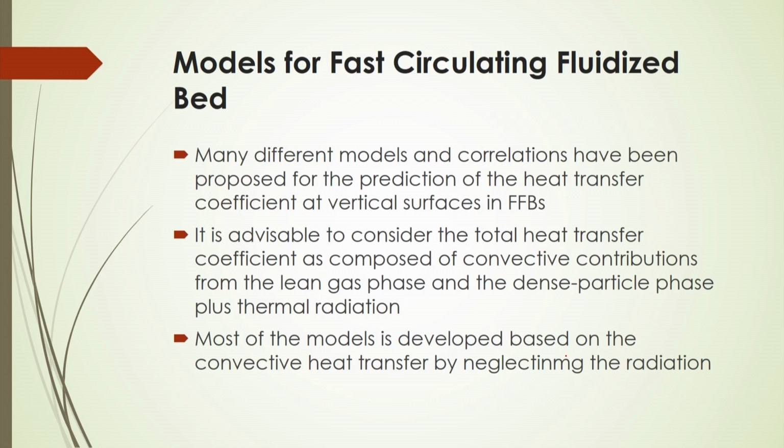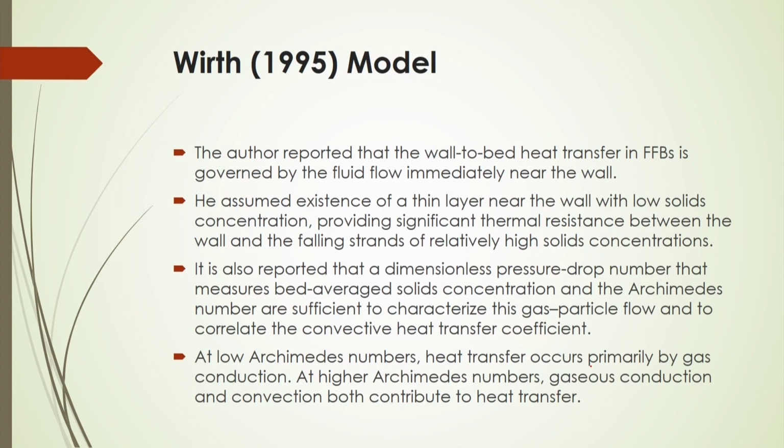It is advisable to consider the total heat transfer coefficient as composed of convective contributions from the lean gas phase and the dense particle phase, plus thermal radiation. Most of the models are developed based on convective heat transfer, neglecting the radiation. There is one important model, called the Wirth 1995 model.